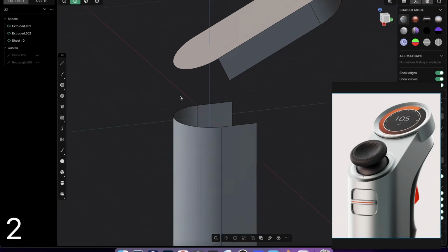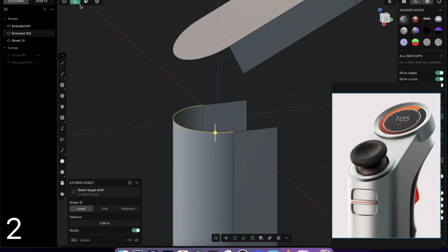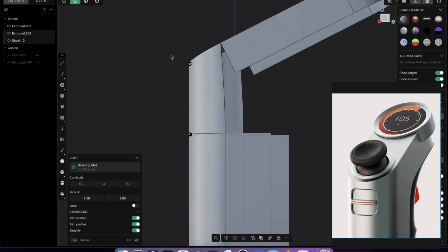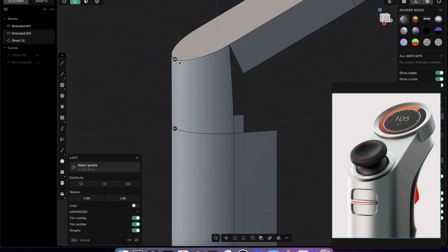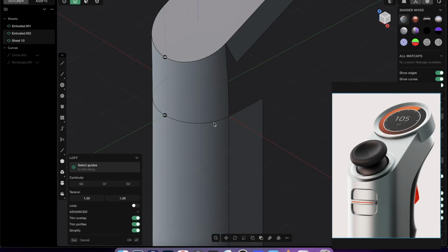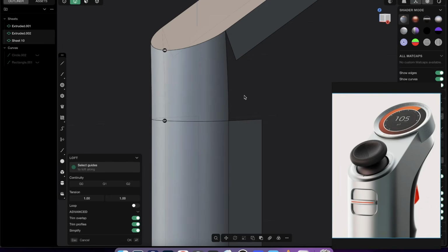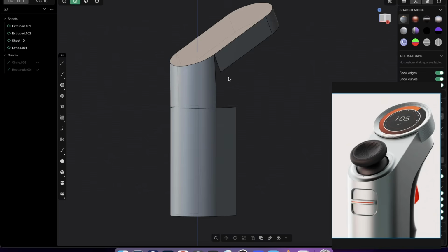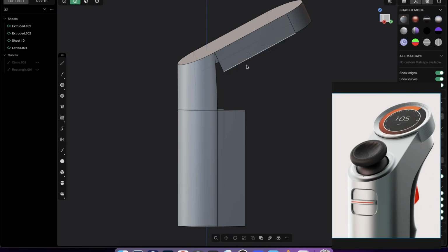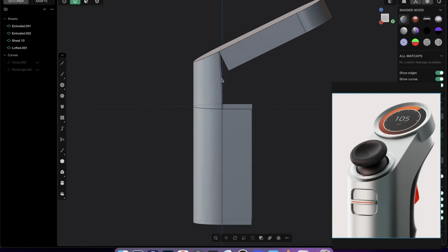And now you can just select this edge in edge mode and this edge and press L to loft that and select here G0. So obviously we just have a sharp corner, right? So as we have here. And here you can just leave a G1, so we just have a nice continuous surface. Right click, and now we have to fix this situation, right, to connect that. But this is very simple.